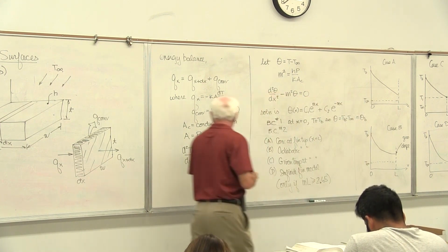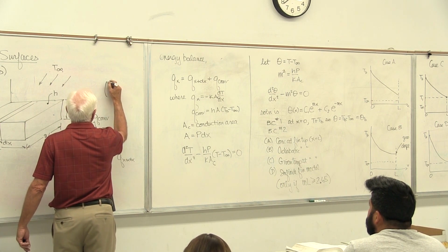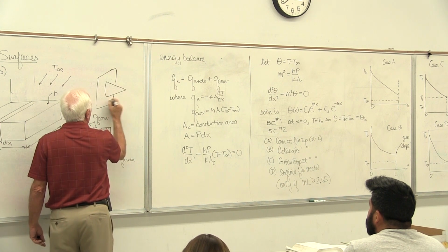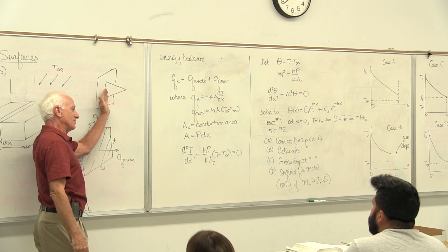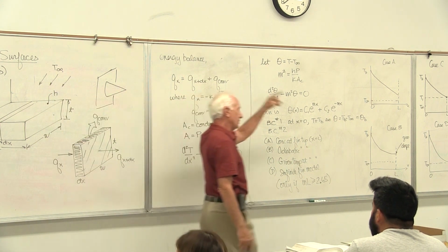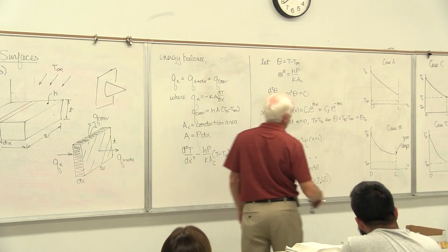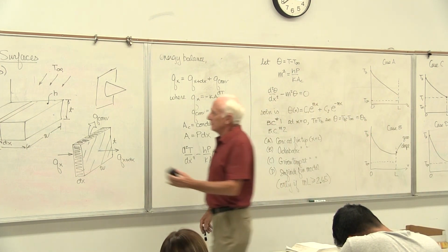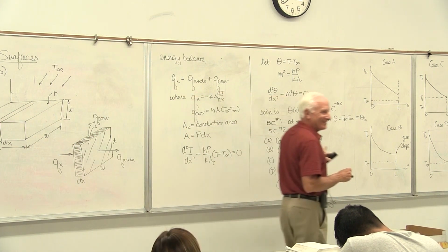But now, if you've got a triangular type pin fin that looks like this, attached to a wall, oh no, don't go to Table 3-4. Now when you slice it normal to the x direction, the area gets smaller and smaller as x increases. So you wouldn't use that table for that fin. So that's what it means when they say uniform cross-sectional area. How does the area change with x? Okay, now, any questions on that before you go on?